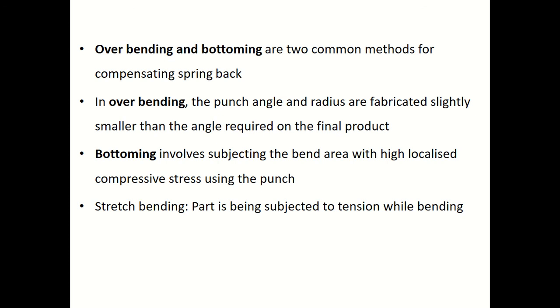I hope you are understanding. And then finally, another important method is called the stretch bending. So the part is subjected to tension while bending. When it is bending, you apply a small tensile load. So this also ensures that the part acquires the desired value after the bending is over.